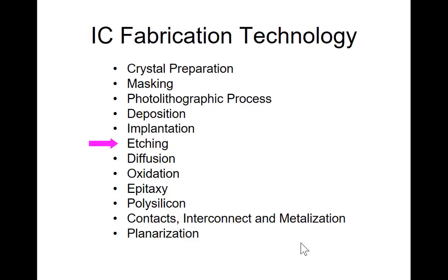And then etching. Etching is a process where you take away some material. Again, the part that you don't want to take away is covered by your photoresist material that is hardened and doesn't dissolve in acid. For the part that you want to take away, you let it be exposed to the etching material, for example some acid.